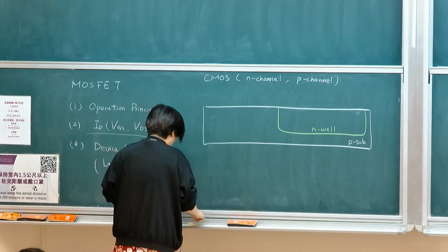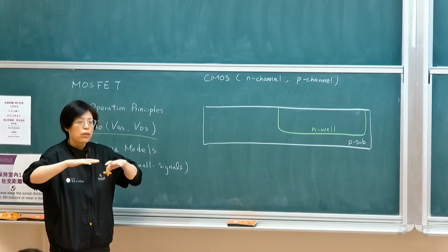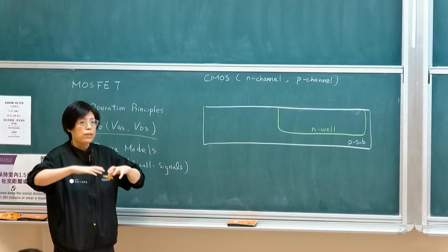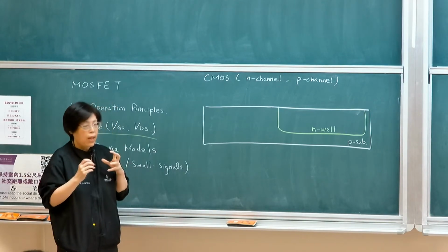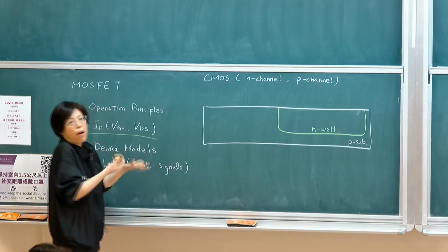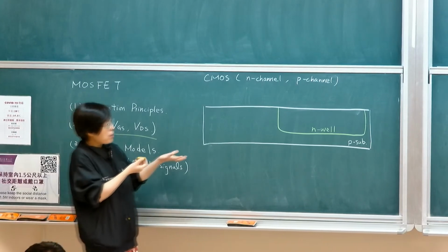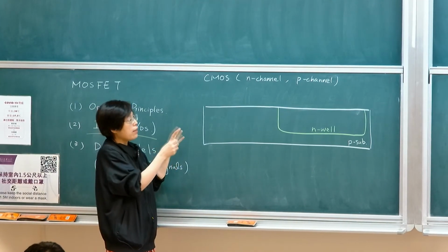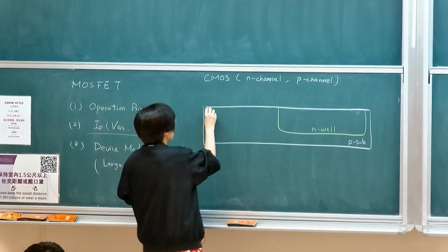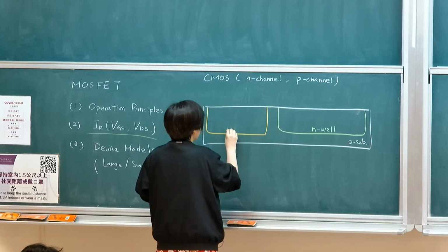Okay? And then if I want to control the doping concentration where the transistor is being placed, the more modern ways of making CMOS technology is that it creates two types of wells. So it will then create something called a P well.